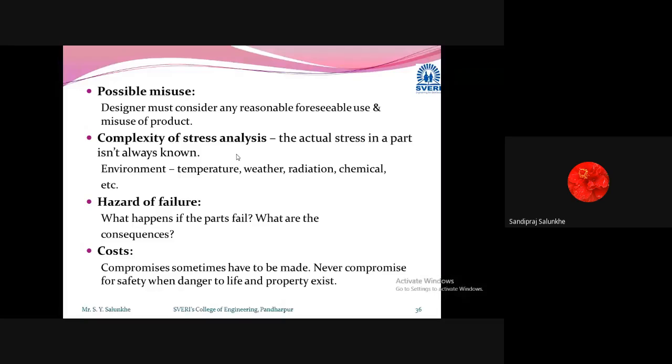So when we are using a factor of safety of 5, and when we are choosing the design load as 50, then you can see the denominator, that is area. If you are choosing 50 as the working load, then the area will be more as compared to the load which you would choose as 10.